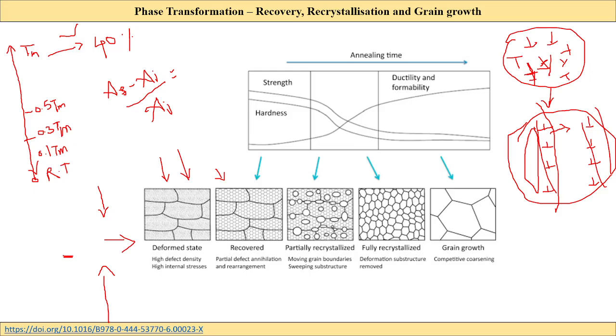And if we give enough time, this rearrangement will happen until the whole system has minimum energy. That means whatever stresses are there will go on dissociating, and more dislocations will be annihilated, the vacancies will be dumped into the grain boundary regions, or with the help of vacancies the dislocations will climb, right? So the vacancies will get annihilated there. All these different types of processes will happen inside the material when we give enough temperature or enough energy to the sample.